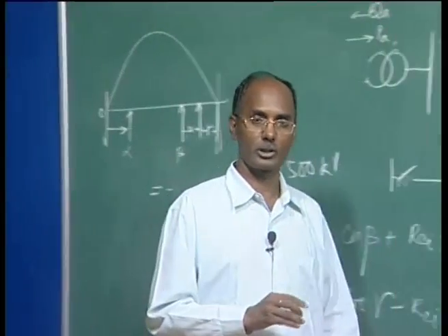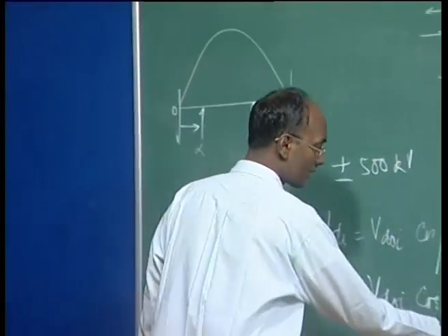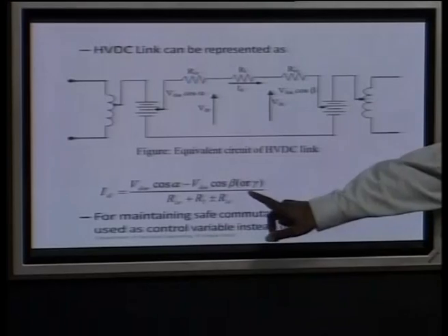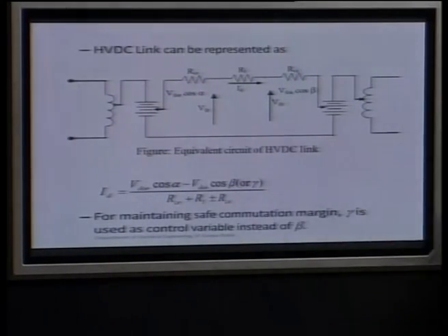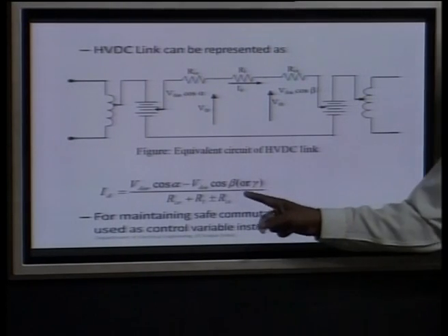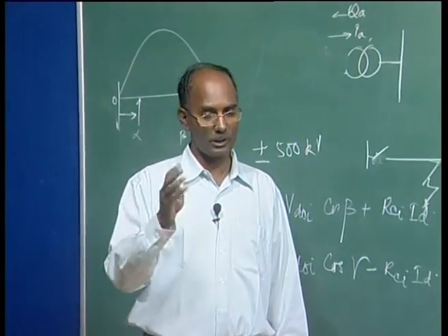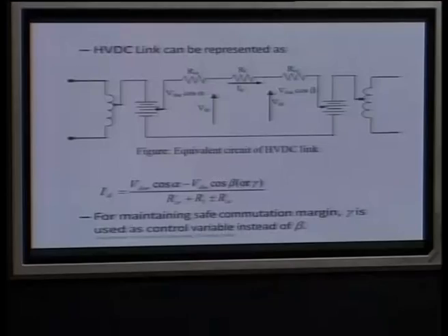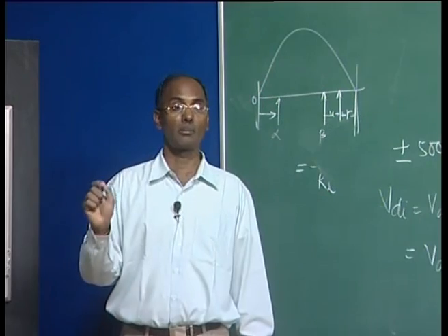The only problem in this controller is the negative resistance. You can see in this expression, if you are using gamma, we get the negative resistance. It is not a real resistance, it is effectively due to the inverter operation, and this negative resistance makes it very difficult to operate that controller stably. So, very carefully, normally this type of controller, we do not change too much, so that there should not be any stability problem of the controller at all.